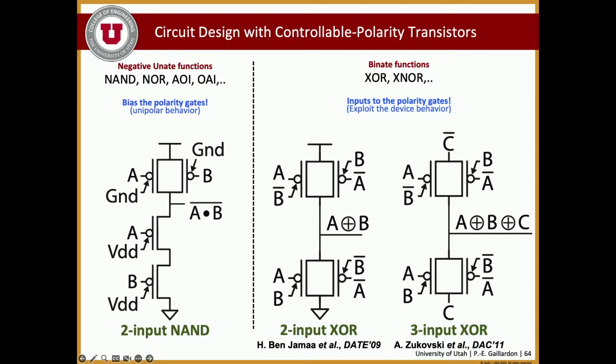So that's, for example, our 2 input XORs. By the way, we can also create a 3 input XOR. This slide is actually pretty poor because we do have ways to implement NAND gate with only 3 transistors using the other stuff. But I pass on the details again. What is important here to understand is